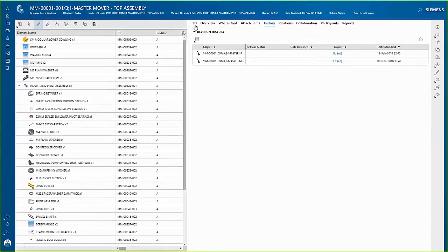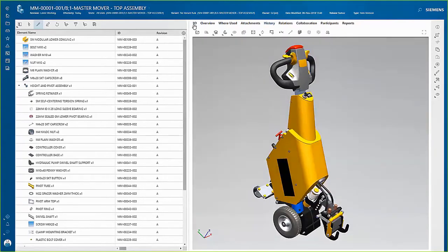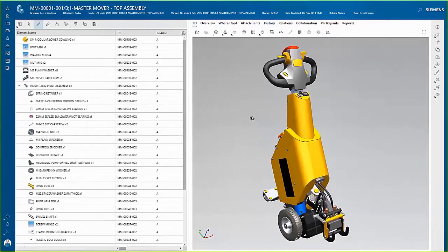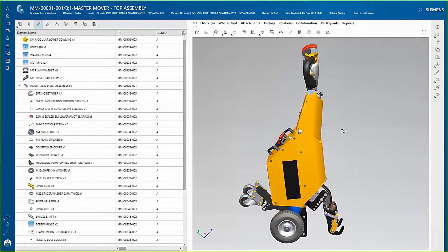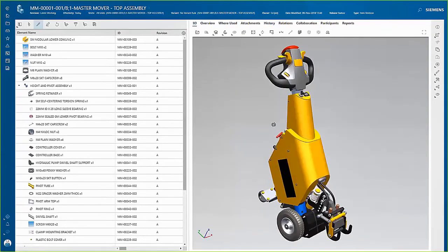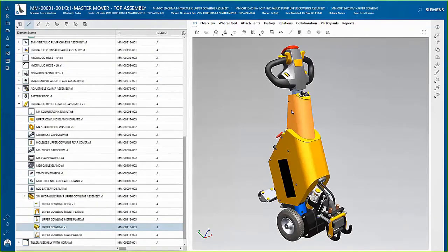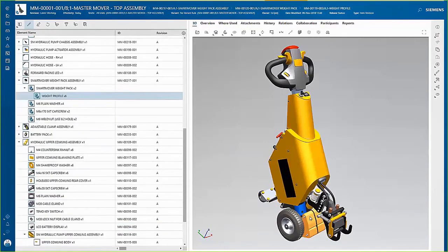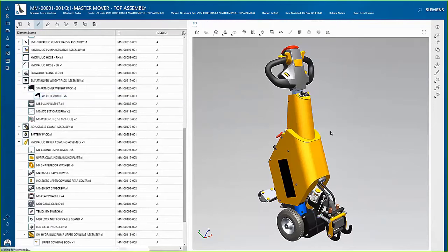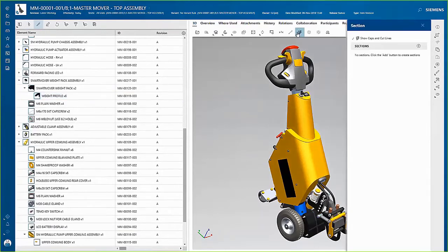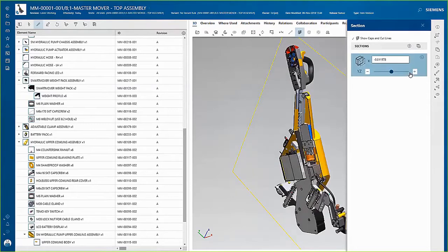You can use visualization capabilities of Teamcenter to graphically interact with the product. You don't even need access to the CAD system they were designed in. They may have also been designed in multiple different CAD systems. The Teamcenter visualization capabilities allow you to visualize all the data in common JT format. You can also take measurements or sections to further analyze the makeup of the parts in the assembly.